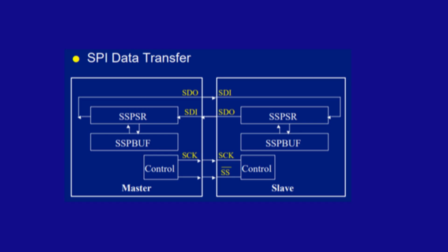Pretty much. The slave doesn't inherently know if it's receiving a command, an address, or data, or how long the total message will be. It just sees the clock pulsing while its CS line is low, and it shifts bits in on MOSI and out on MISO according to the agreed-upon SPI mode, CPOL and CPHA. Synchronization is maintained purely by that shared SCLK signal generated by the master. Both devices use the clock edges, as defined by CPOL and CPHA, to know precisely when to shift the next bit out and when to sample the incoming bit.